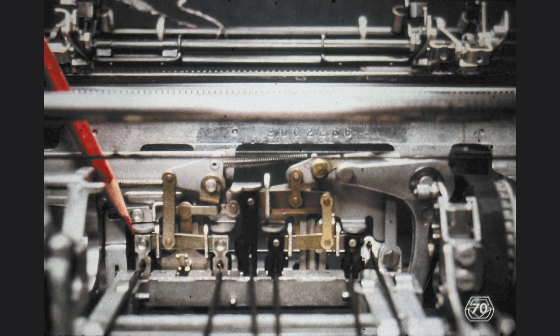Now the amount of motion transferred through the link to the bell crank is going to be exactly equal to the amount of motion obtained from the cam follower, since both latches are pulled down. This results in 3 tilt increments of rotation for the type element. We are thus in a position to print the character located in the 4th character band of the type element.